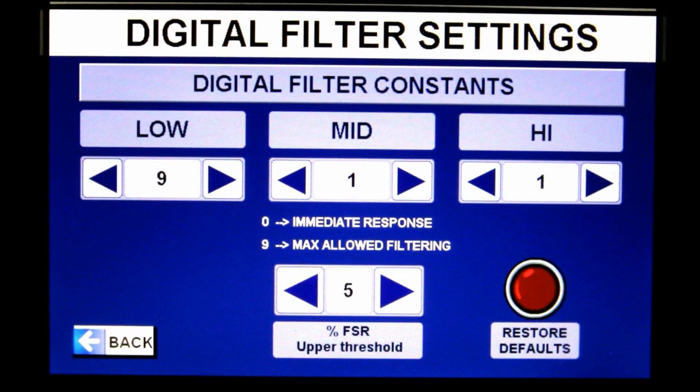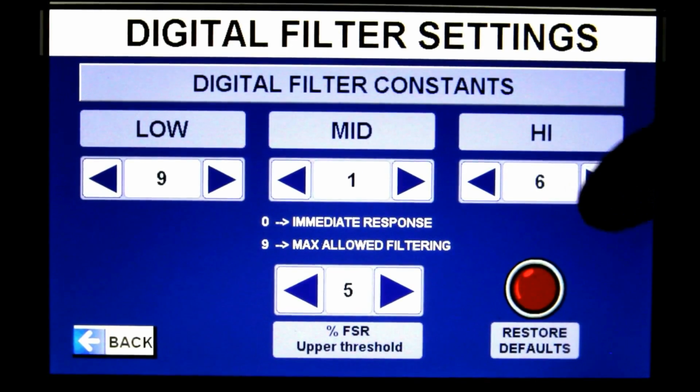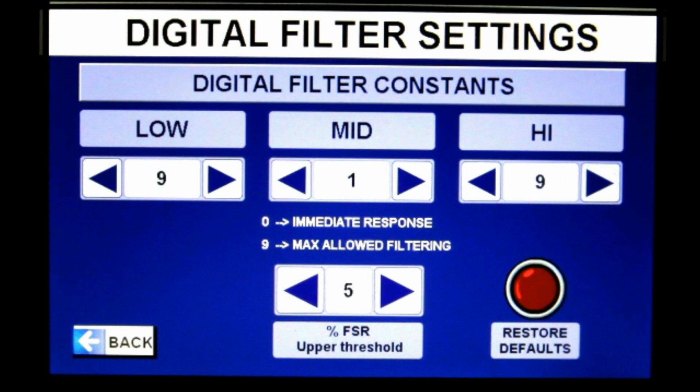The digital filter settings allow the user to dampen out periods of random fluctuations in the flow rate readings that tend to obscure the true values. In the filter section of the configuration menu, the user may select a filter value anywhere between 0 and 10. The higher the value, the more dampening. While the filter does not affect the average value of the leak rates displayed, it does affect the indicated fluctuations of leak rates with respect to time.